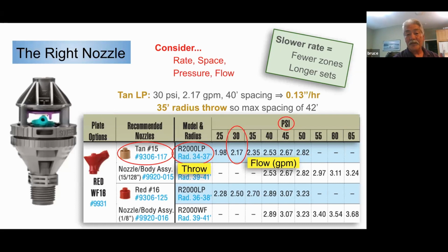utilizing one sprinkler. For example, if we were doing that nursery and we decided to go to 32 feet, we're going to be having that many extra rows of sprinkler heads, where the 40 feet will work properly. We're looking at 60% of the diameter of that sprinkler head. So we're looking for a sprinkler that's going to match for a 40-foot spacing. And then we want to look at an application rate that's going to adhere to the soil that they have.